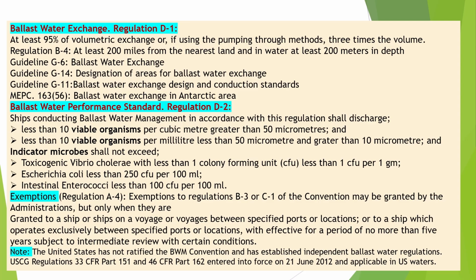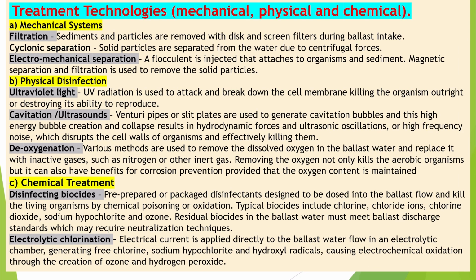Note: the United States has not ratified the BWM Convention and has established independent ballast water regulations. USCG Regulations 33 CFR Part 151 and 46 CFR Part 162 entered into force on June 21, 2012 and are applicable in U.S. waters. Treatment technologies: mechanical, physical, and chemical.